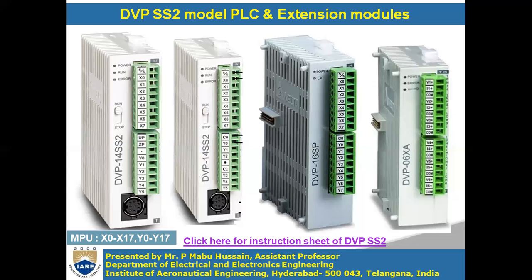So if your experiment has analog inputs or analog outputs, how can you use this PLC? You cannot. In such a case you have to add the analog extension module. This last one is the analog extension module. You connect this analog extension module to this PLC, or you can connect it on the backside of this also.